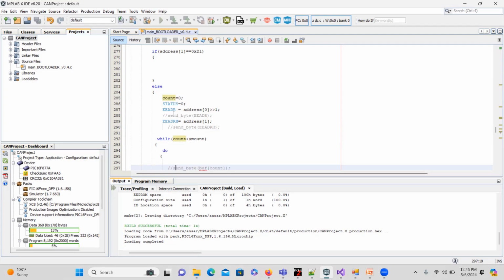That means the LSB of the EEPROM address. For that, I am storing it. But while storing it, I right shift by one time. Why are we doing it? Because in my file, we have totally 3 program data. Each program data is 2 bytes in size. That's why we get 6 as the data size, right?